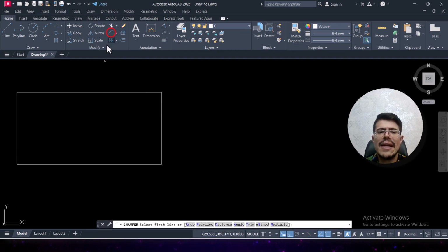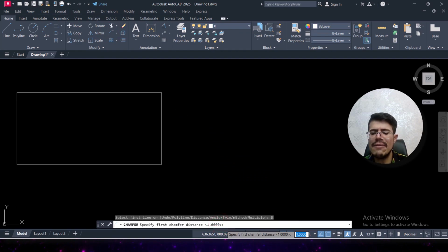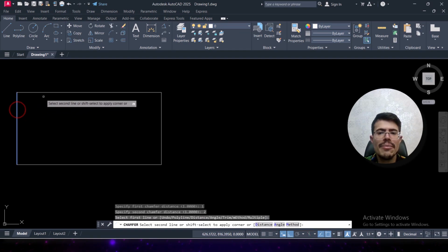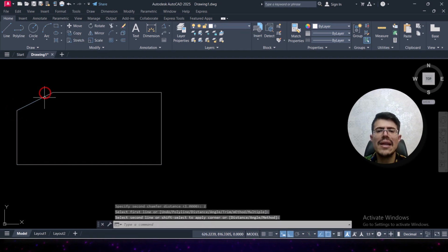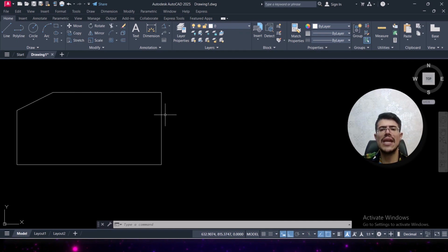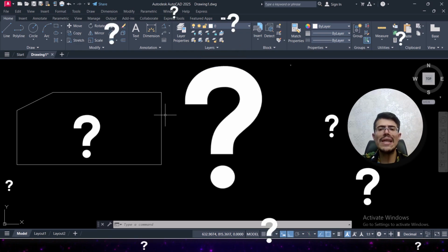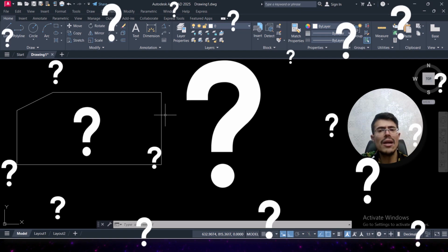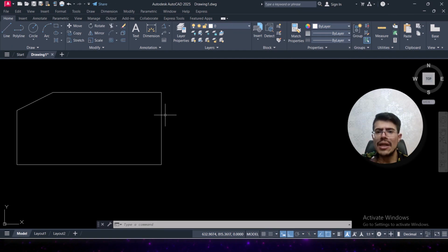In here, I select a chamfer. As you understood till now, if I select the value of 1 and 2, and I select this, be careful to this part, by selecting on this, it goes out of my command. So maybe I need to do the same case for these edges too. Do I need to do it and recall my command again? With this manner, yes, but in Chamfer, we have also another capability.